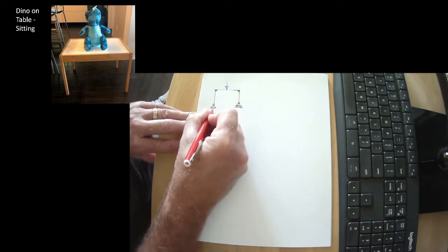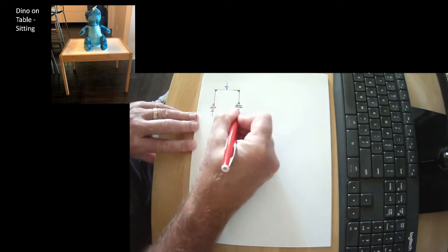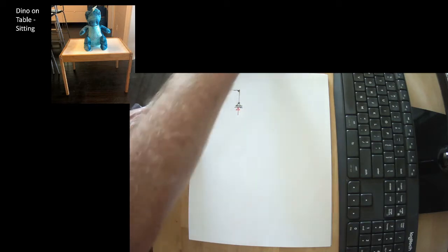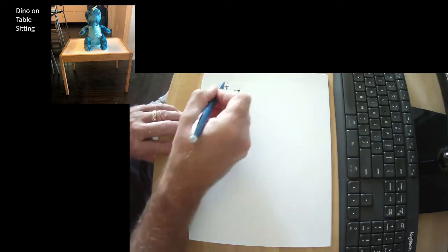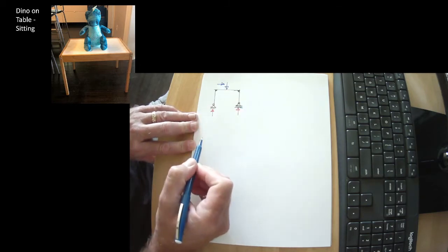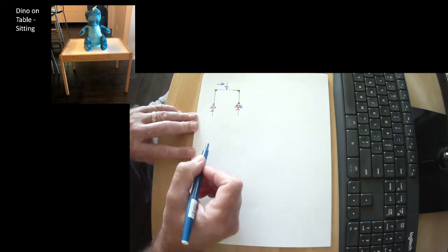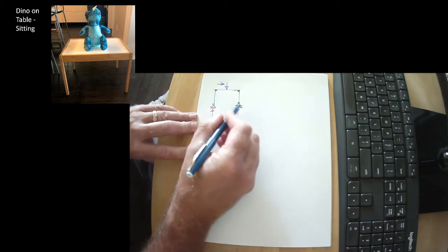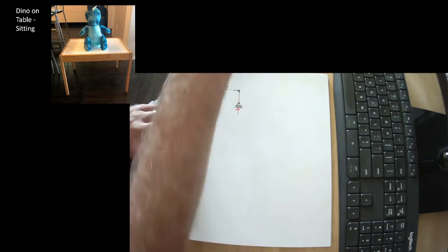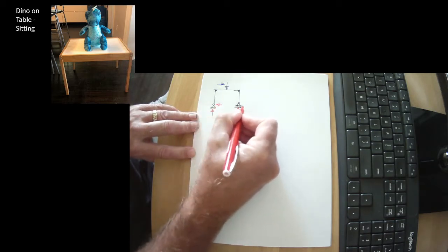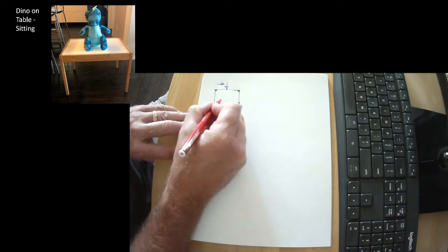So what are the forces that we need to hold it in equilibrium? Well, Dino himself will be balanced by 2 vertical loads. Recall that we had the potential to have wind on Dino, like this. How does that get resisted? Well, we have called this a pin and roller, which means that the horizontal load can only be resisted at the pin.